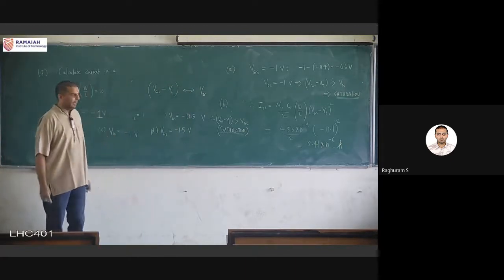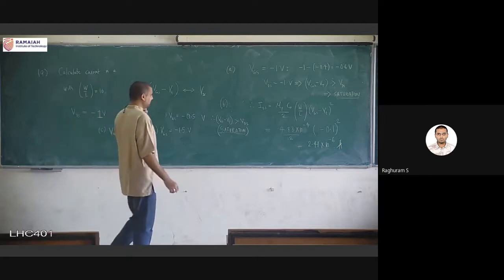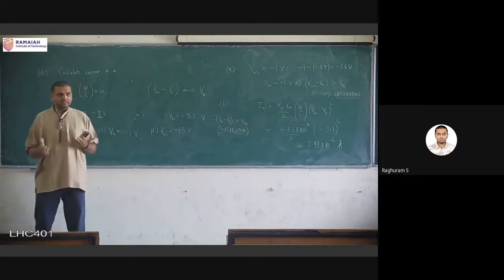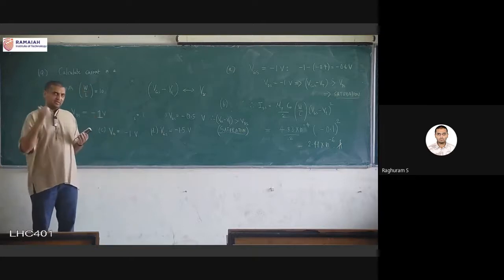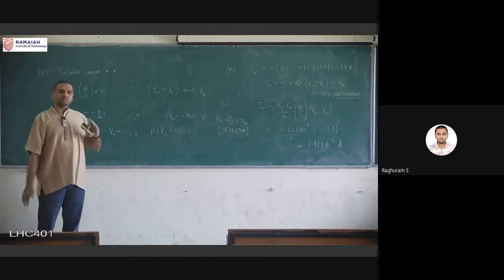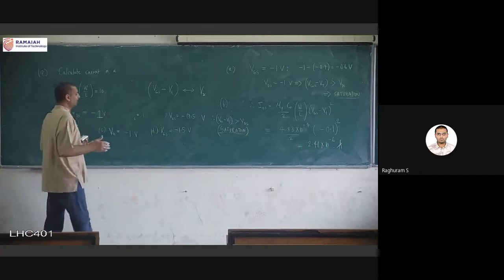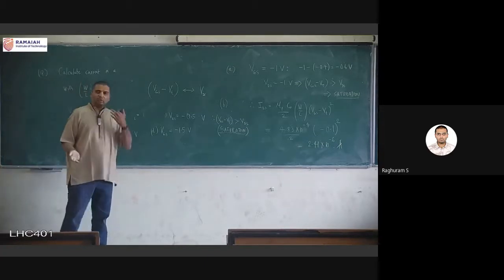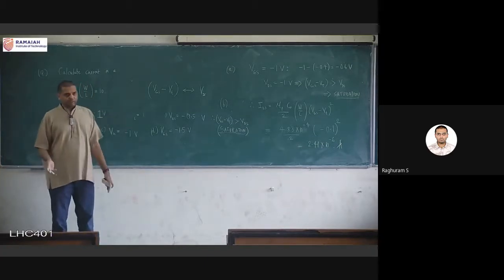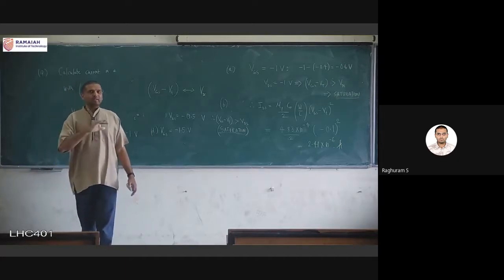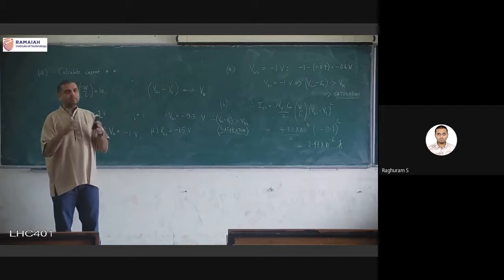Always remember the condition for Nmos clearly. Remember one set of conditions for on, linear, saturation. If it is Pmos, reverse all the conditions, then you will get the correct conditions for Pmos. And at the end, there are two separate equations for the current also, one for linear, one for saturation. There also we can use a little simplification. Remember the linear equation, the longer equation, properly.